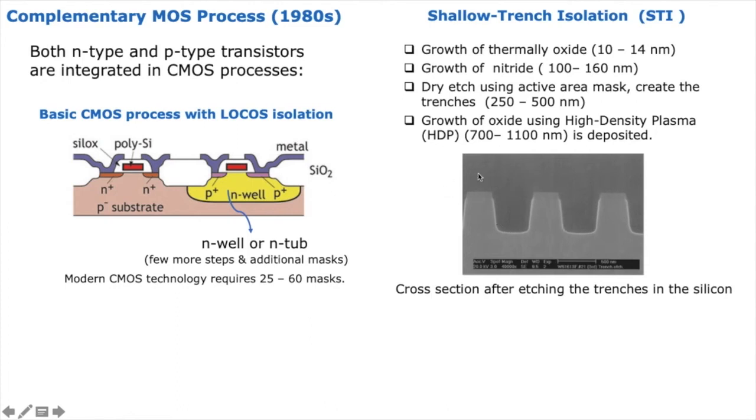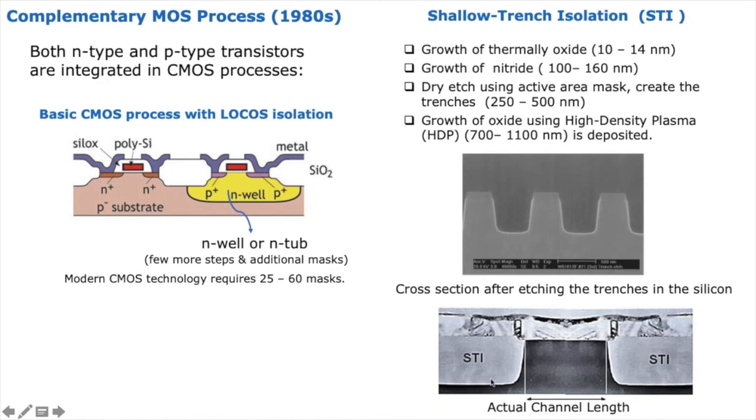Now when you do the oxidation, this is silicon, so you fill this part with silicon dioxide layer, and then you have two separators, right? This is oxide, this is also, and this part will be silicon. So eventually you have STI here, this is where it usually goes.